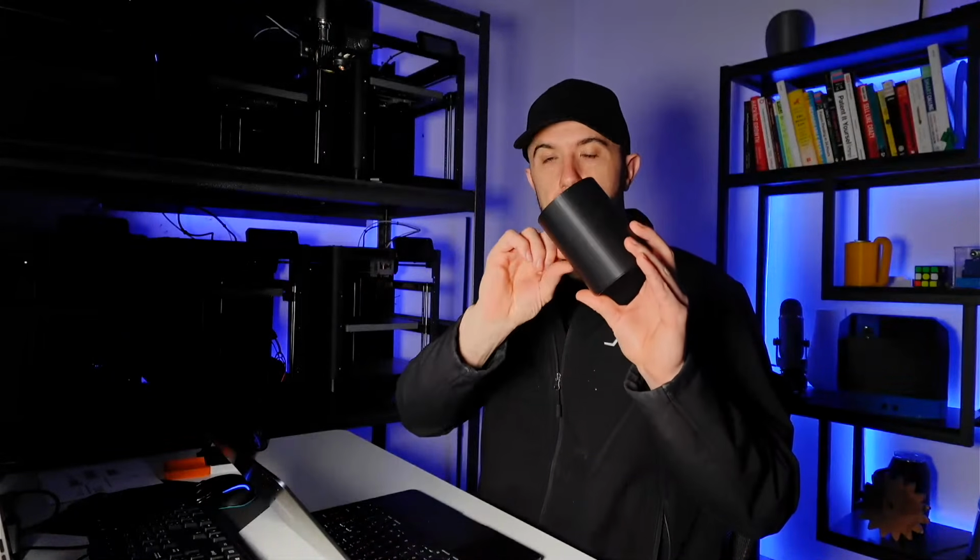The other option, if you're doing the fin design, where you have a sideways mounted part just like this and you want a support fin right there, is you have the support pin running along the edge, about 1 millimeter of distance in there, and then you have horizontal spokes, spines, sprues, tines, fingers. Those are all synonyms. Horizontal, running into the part, not touching, not on the outer edge, not close, into it. It is part of it, so that the support fin is part of the part. And that way you can snap it off and it supports the part in both directions.